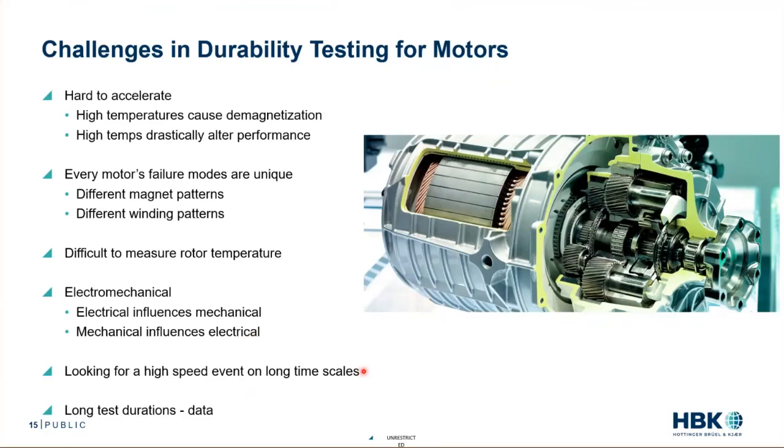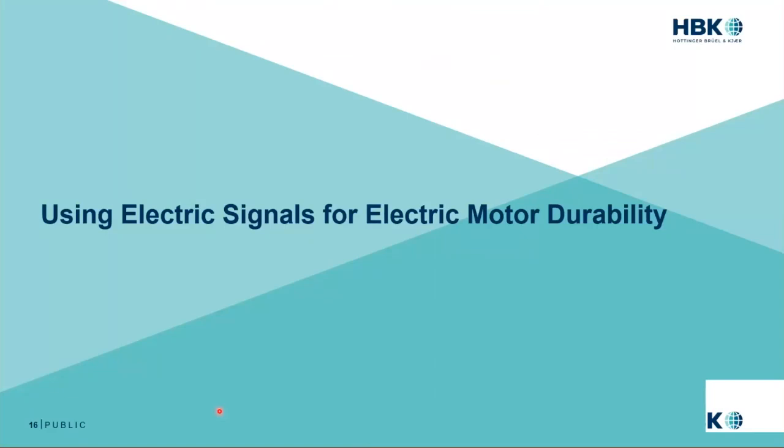Now, these tests are running for tens to hundreds of days. And these electrical failures are very high speed. They're happening in the kilohertz rate. So we're looking for high-speed events on very long time scales. That's always a challenge from a data perspective. And just the long test durations result in some challenges from a data perspective. So these are some of the challenges.